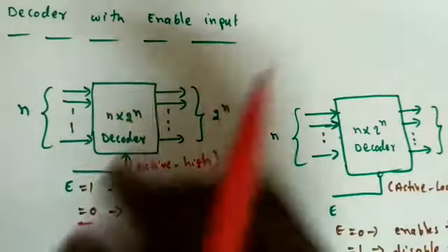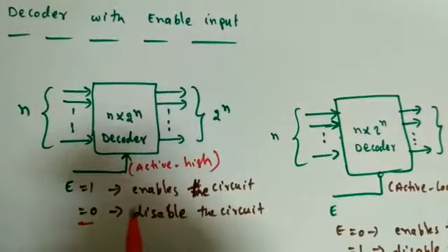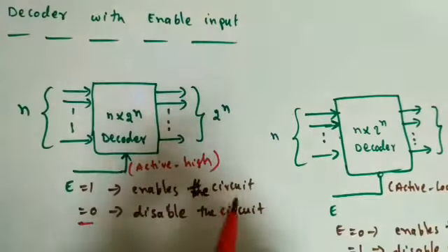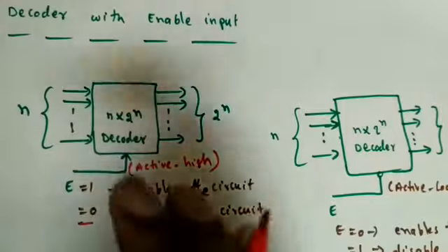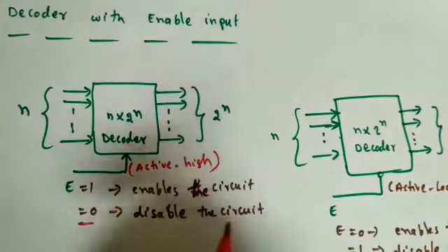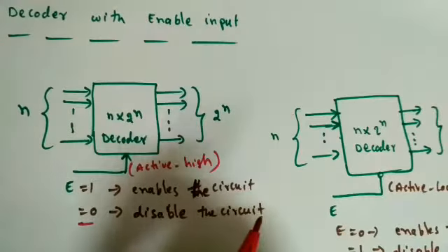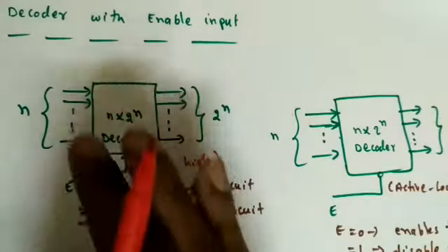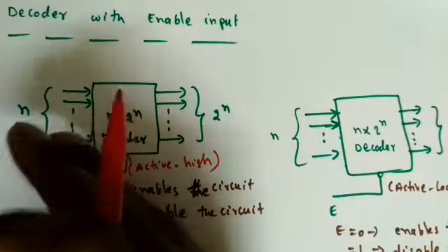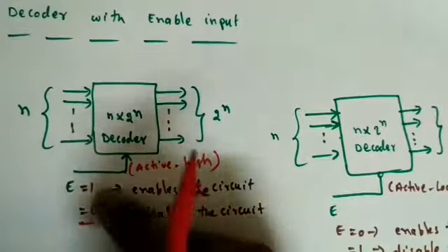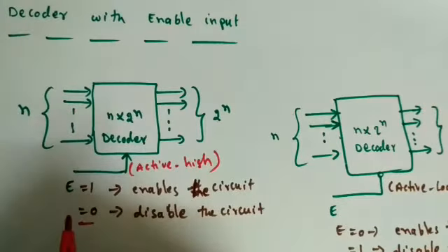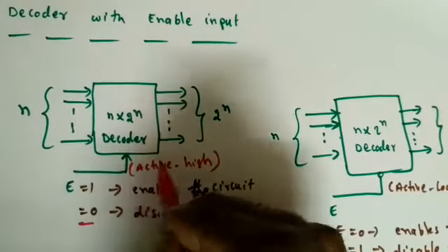Whenever the switch is off, there is no operation. Something like this. Whenever we purchase some ICs, you will always see enable pins. Sometimes we may have one, sometimes two or more. Depending on this enable pin configuration only, it will perform. Even when we give some inputs, if we don't give the enable pin as high, it will not perform the conversion. So this is active high.